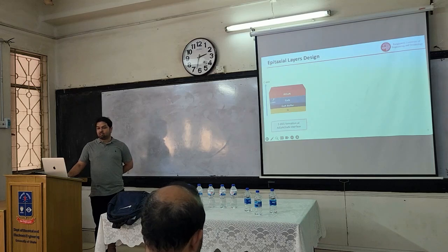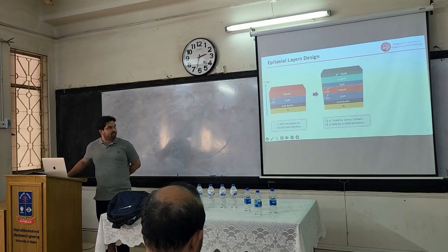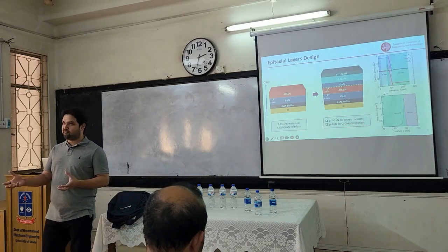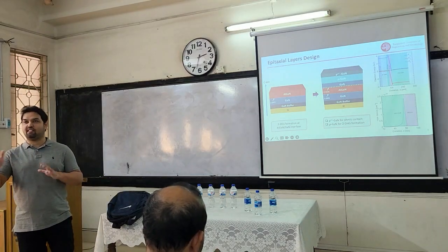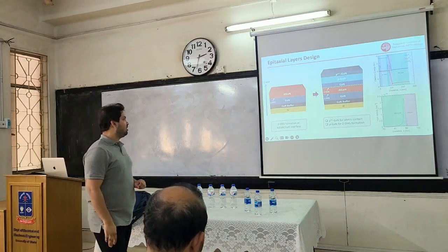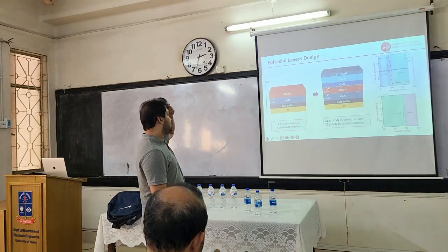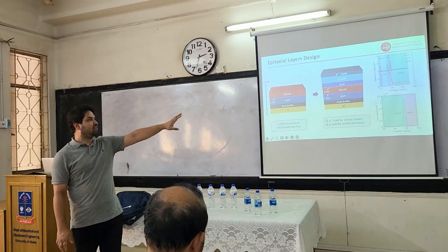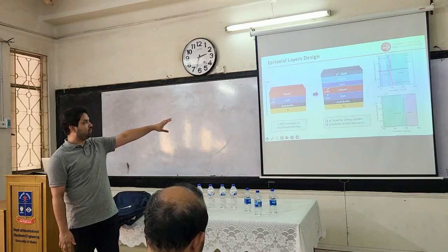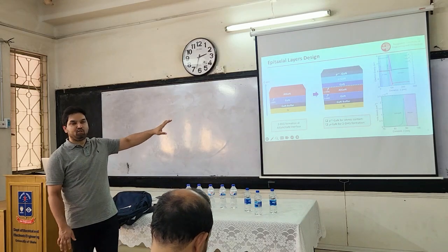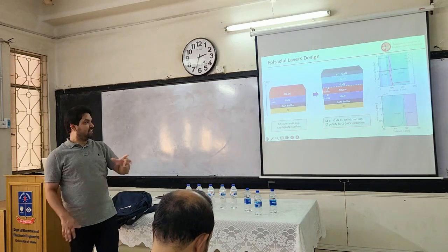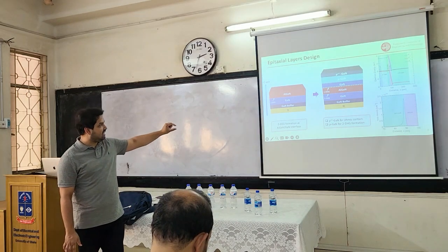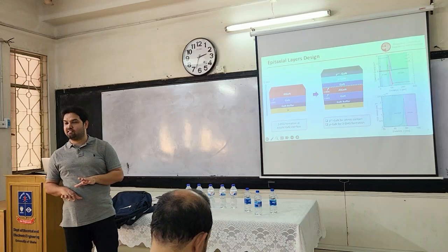Okay. So basically, if you want to have N-type and P-type transistors, you need electrons and holes in the same wafer. The way to do it is you grow, these are all on silicon, a GaN buffer. The purpose of the buffer is to manage the stress between the silicon and GaN because they have different lattices.